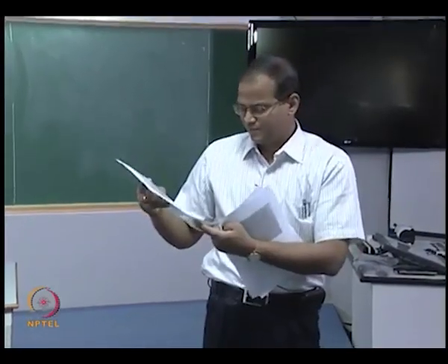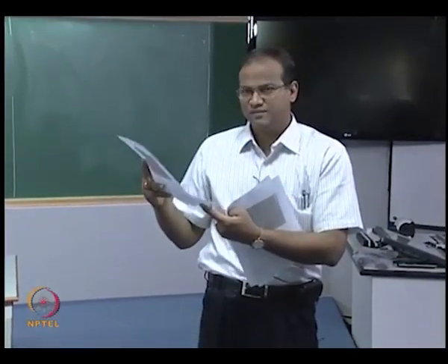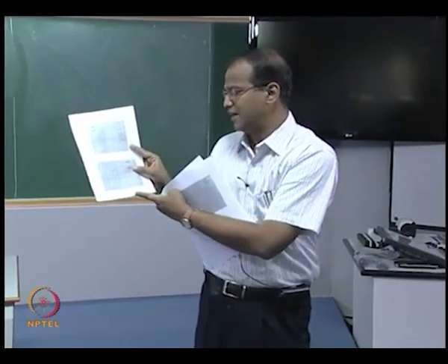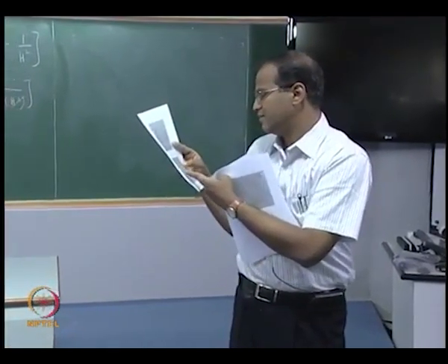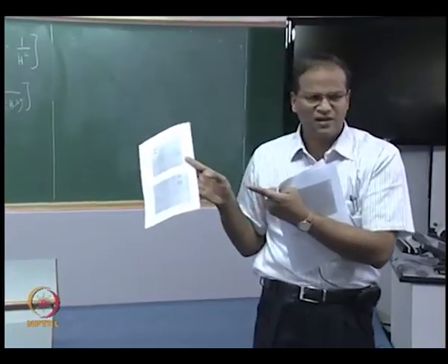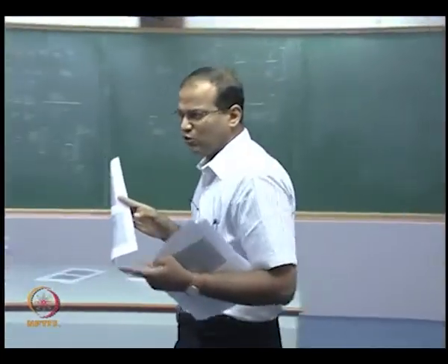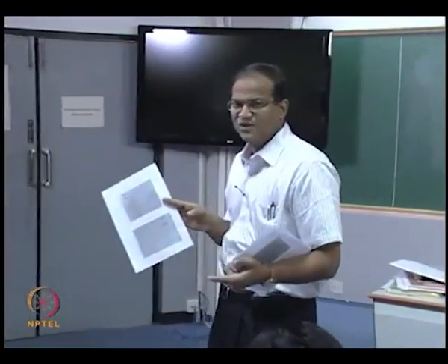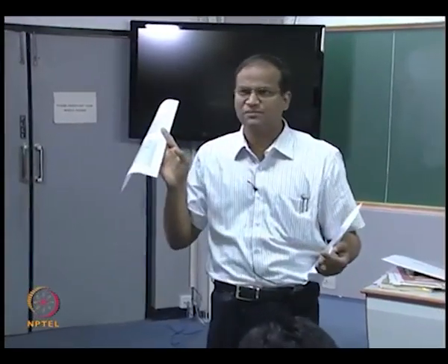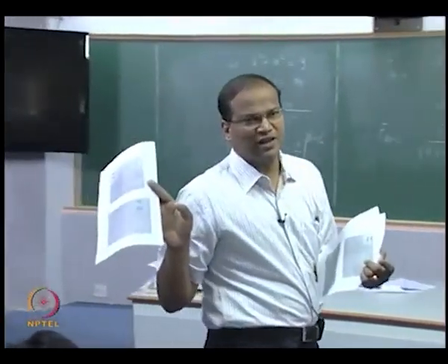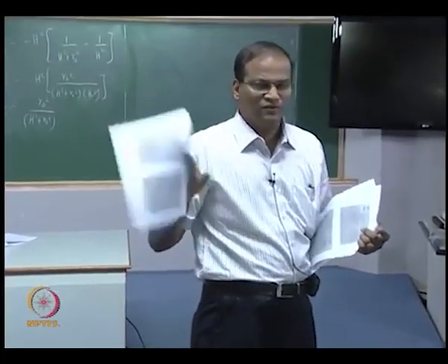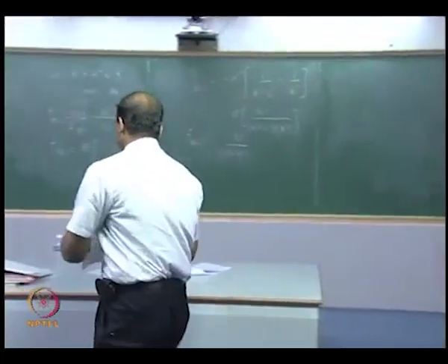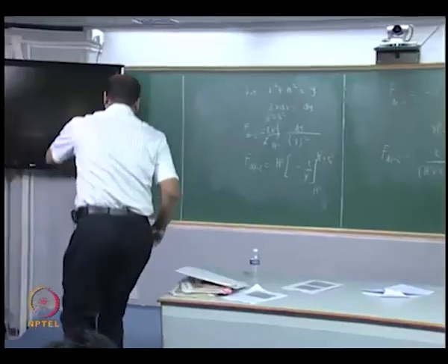So L by Ri will be on the x axis for the 2 coaxial parallel discs, then the other variable is basically Rj by L, please look at it carefully, right. If it is not okay, you can make corrections now itself, you are going to use it in the second quiz as well as the exam. Okay, fine. Now let us use this and solve some problems.